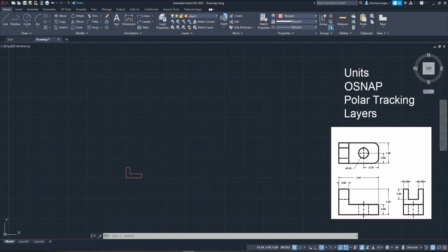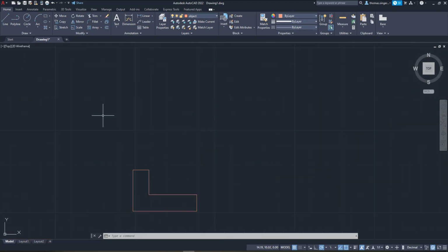The second shape is up above, and again that's a 1-inch thickness by 2 inches long. So we'll start the line. And here's a little tip. If I come to this top corner and just highlight, don't left mouse click, just highlight. Okay, if I just highlight, no left mouse clicking, no picking, I just move my crosshair on there, notice how I can get this green dashed line, and then it lines up with that edge.